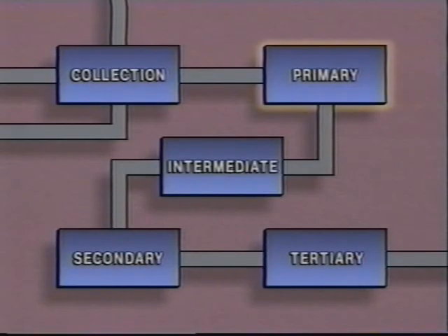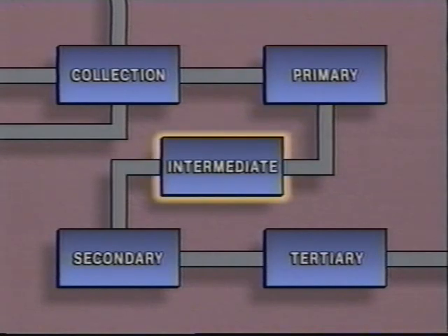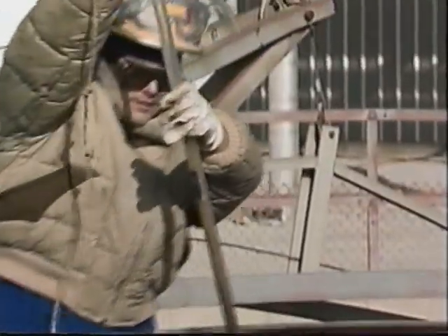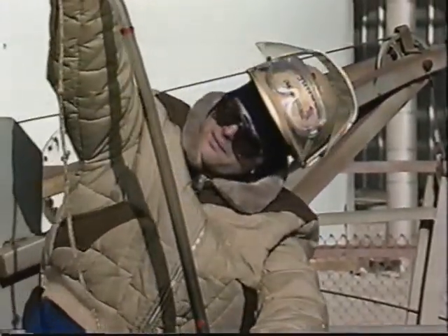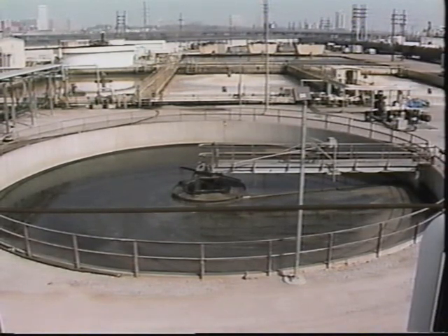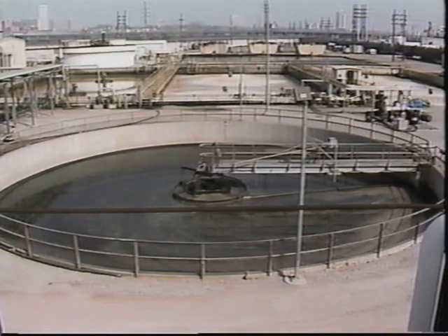In this system, there's a clarifier in the primary, intermediate, and secondary treatment stages. In this case, it's the clarifier in the secondary treatment stage that has the high sludge blanket level. A high sludge blanket level is the type of problem that, once it begins, tends to work its way downstream in the treatment system. The sludge in the secondary treatment stage is activated sludge, and this affects some of the preventive steps needed for this problem. Activated sludge contains microorganisms or bugs that eat organic material in the wastewater.